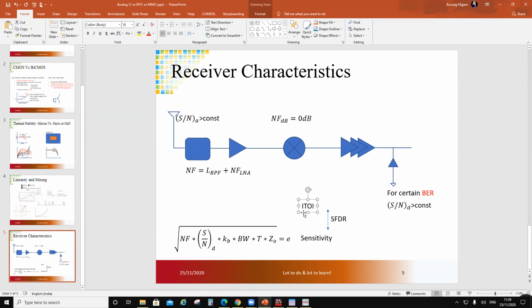So once we know this, we know that there is certain gain. Okay, so once we know that, we should keep maximum gain on this side, but then you will distribute the gain over here. Okay, now what's the problem putting maximum gain on the LNA? The problem is that the mixer limits the compression point.